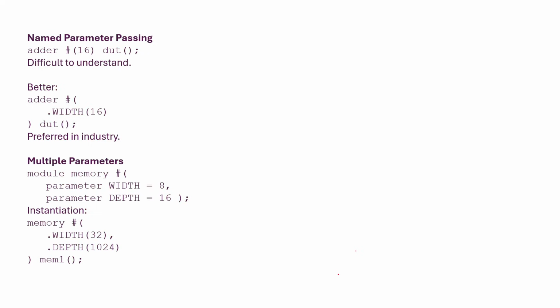So this is name-based parameter passing. This way we are utilizing it. In most cases we write these name-based parameterized modules. Instantiation we go for the name-based, and our module also we write name-based only. Position-based will be tough for instantiation because we need to check the input and output ports are in the same order. If you change it, the values will still be taken, but different values will be taken. Then we need to check everything. That would be the problem.